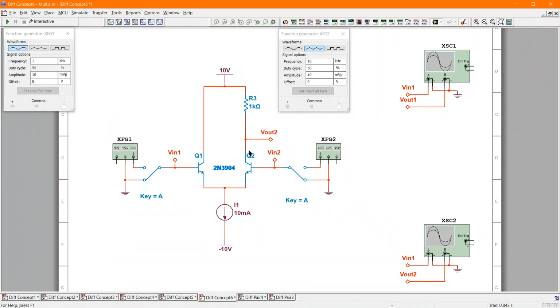If you only need one output, so if you want a differential amplifier which has one or two inputs and only one output, then you don't need the second resistor here. Current-wise, it's the same thing. If I put a signal in here and I generate a base current, that'll get amplified and I'll get a collector current down here.